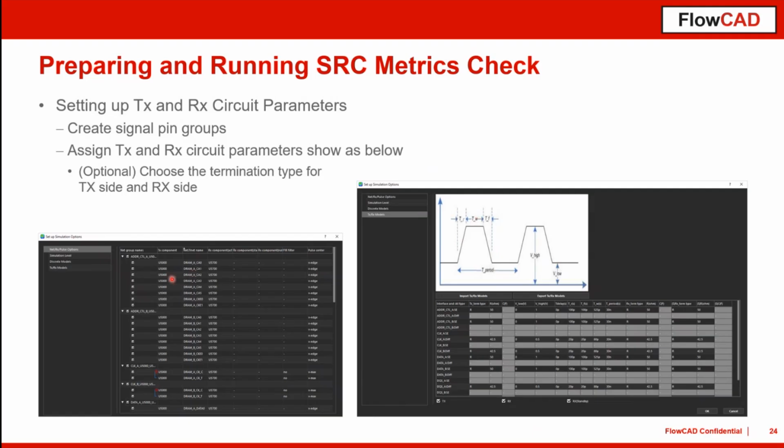The devices themselves, for example, I'm choosing the complete memory bus here, are now separated into the typical memory groups like address, command, data, strobe, and clock groups. That is assigned here in this case. Afterwards, we have to assign the data pattern for the drivers. That is typical, like a PWL as we know it from a SPICE notation, for example. On the receiver side, you can change the on-die termination if the parameters are available.